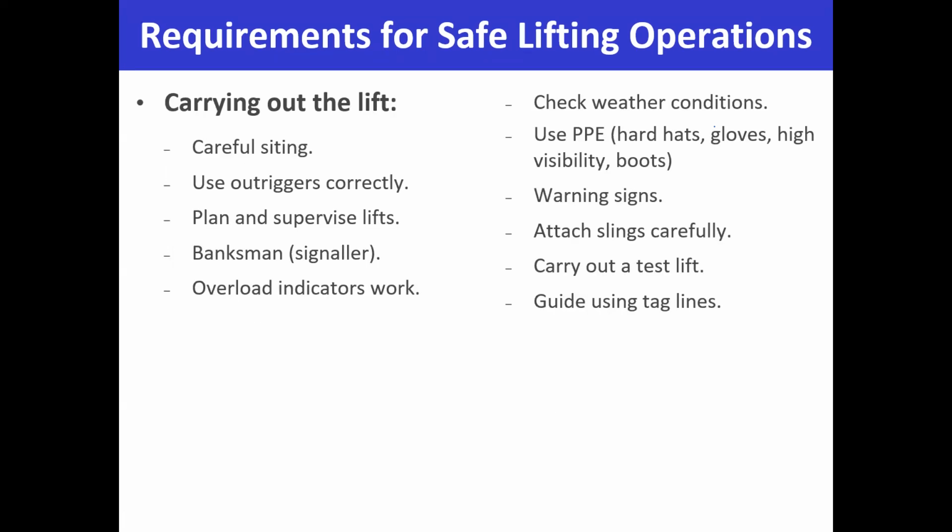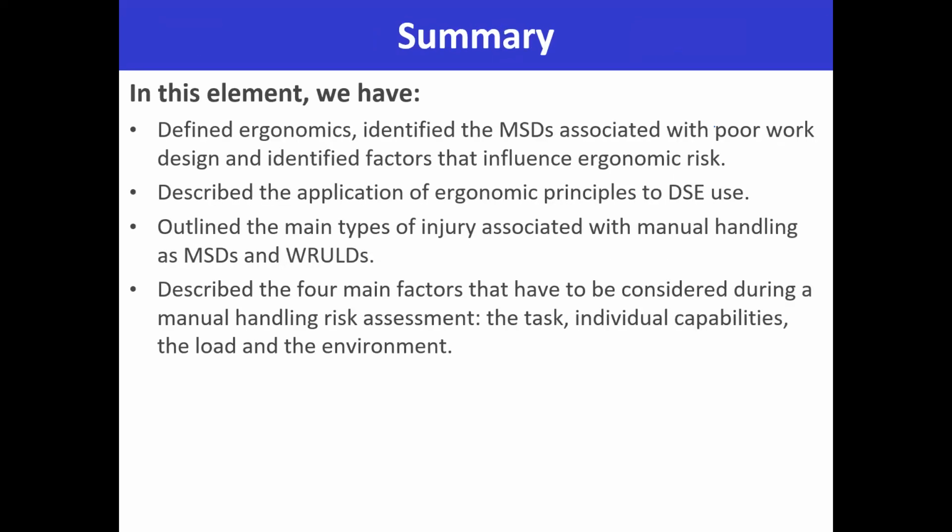Okay, you need to make sure that you carry out the lift after careful siting, use of outriggers, plan and supervise the lift, make sure banksmen or signalers are available, overload indicators should be working, check the weather conditions, use PPE, warning signs, attach slings carefully, carry out a gas test, and carry out a test lift so that you can understand whether the load is going to be lifted or not, and guide the load using taglines.